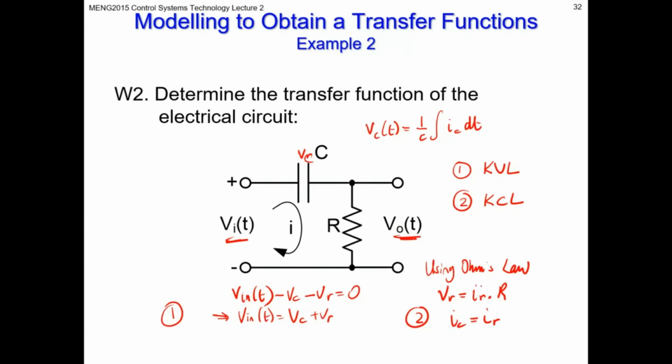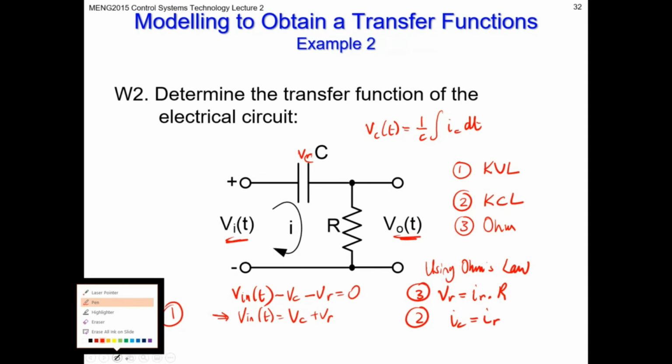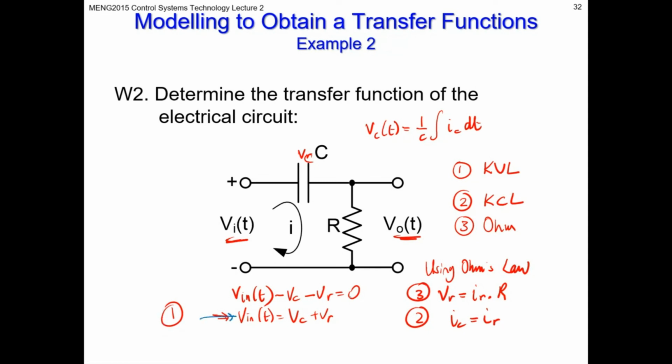So now we have 3 equations: 1 is Kirchhoff's voltage law, 2 is the current law, and 3 is Ohm's law. You can put these 3 equations together to create a transfer function for this circuit.